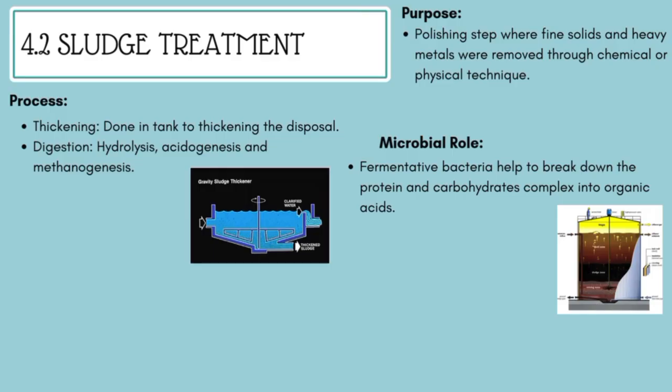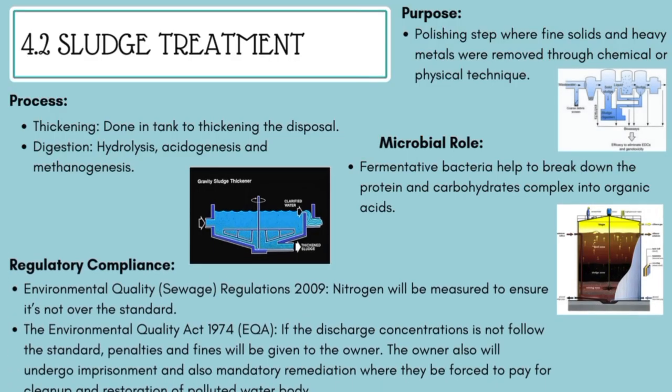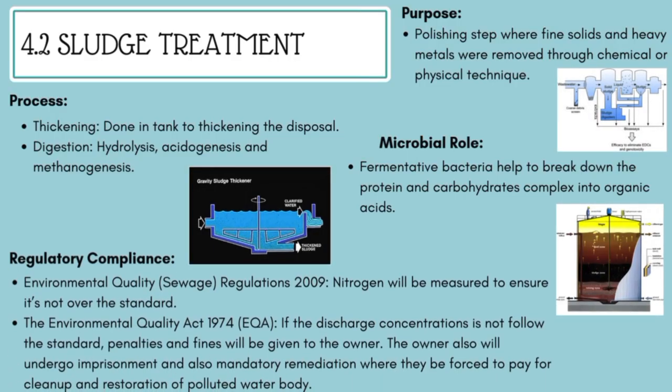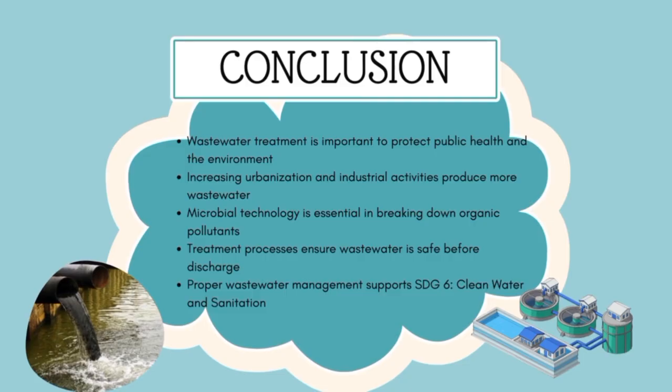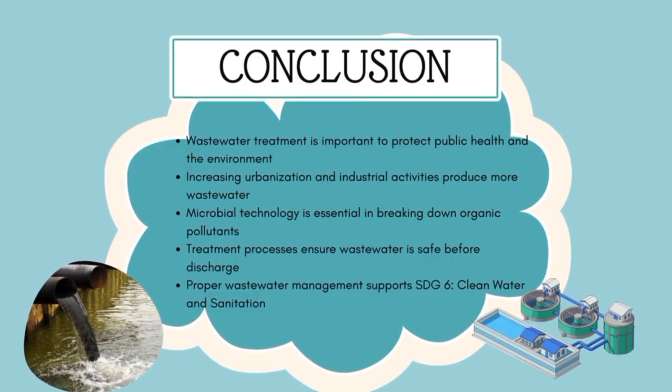Fermentative bacteria break down complex organic matter, while processes like thickening and digestion occur through hydrolysis, acidogenesis, and methanogenesis. Failure to meet discharge standards may result in fines, imprisonment, and mandatory remediation under the Environmental Quality Act 1974. In conclusion, wastewater treatment is important to protect public health and the environment.